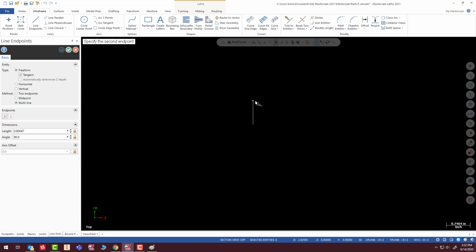Then I'm going to go to the top diameter, the largest, the major diameter, which is 1.625, comma 0, and 1.625, comma negative 0.375. Oops, I hit 2 points by accident. And down to 1.225, comma negative 0.375, and I'm just going to connect it.